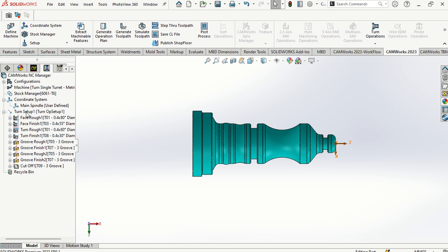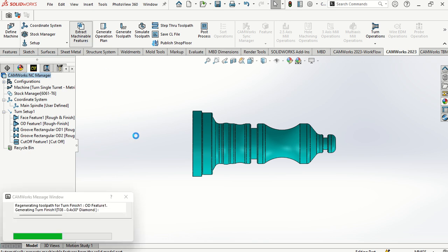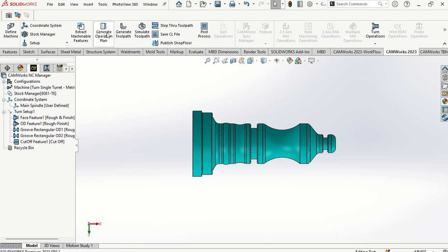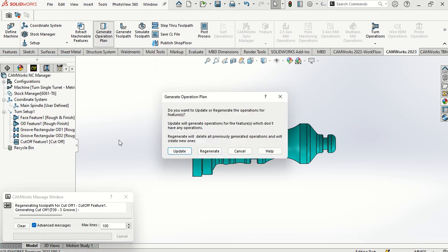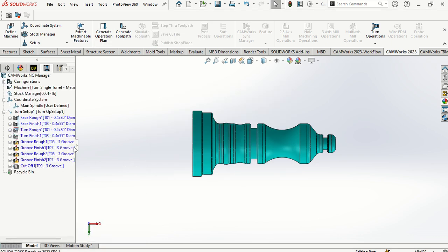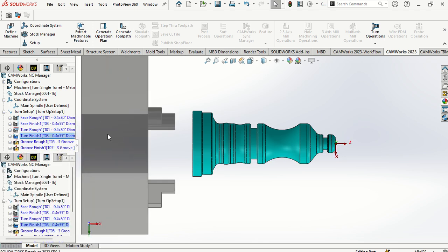Then here I can now say, if you extract the features, it will also extract the features. Say extract the features, machinable features, which machine features can be machined from here. And then you could say generate plan. So you can generate a plan. You can come here, toolpaths, but I want to change this tool, add the tool for finishing.